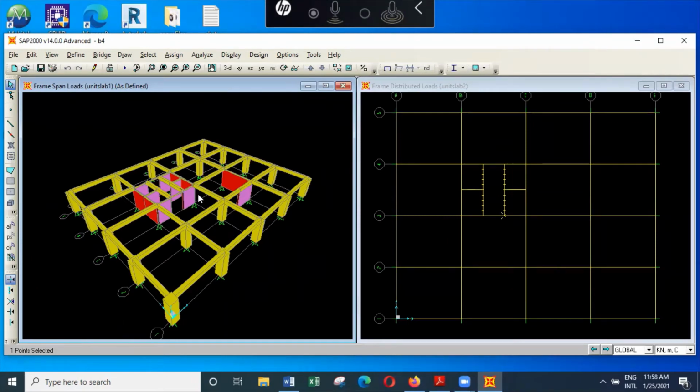So at each floor level, we are getting a 175 millimeter thick slab, and that slab can contribute to the mass of the structure. So when you are doing an analysis, we are looking at two different properties. One is the static response, the other one is the dynamic response. So when you want to know the dynamic response of the structure, then we have to determine the natural period of vibration of the structure and also the natural periods of vibration in higher modes of deformation.